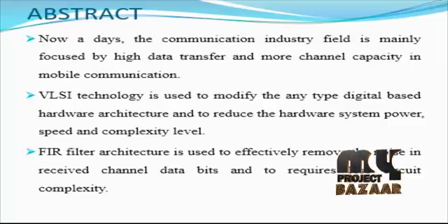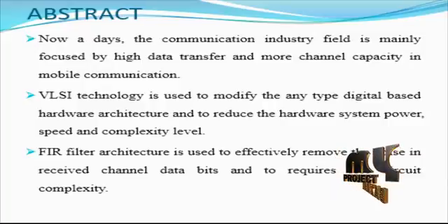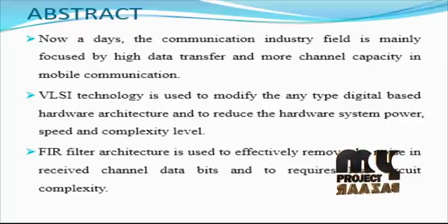An energy minimizing loop uses this to find the minimum energy point and sets the supply voltage at the minimum energy tracking point in our process. In this paper, we present a digital energy sensing that does not require any sort of reference, is robust to process variation and performs well over a wide range of system current consumption.